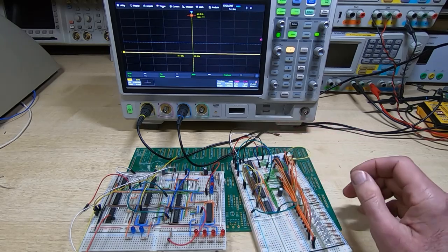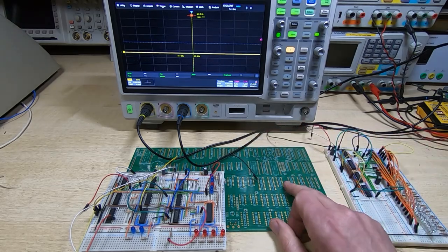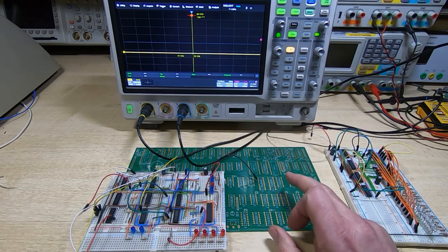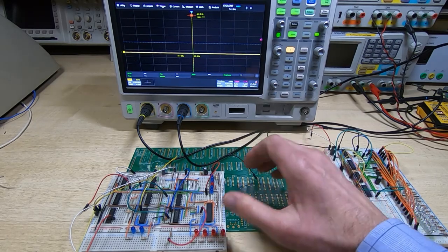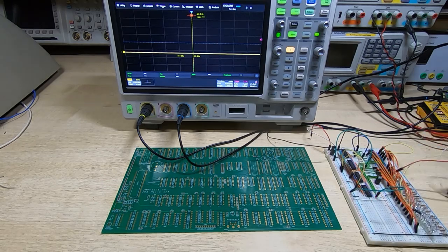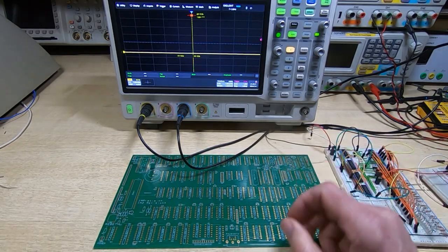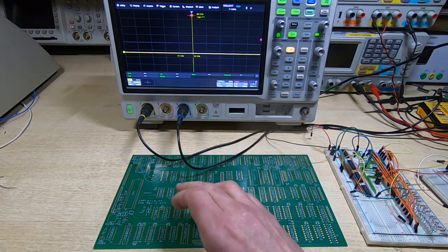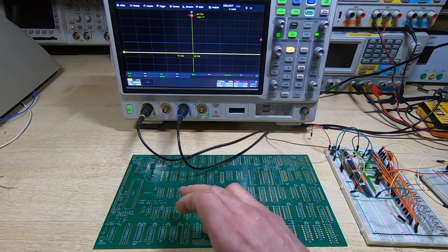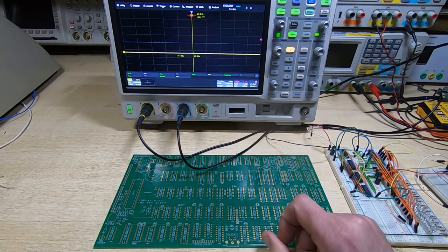So it's quite a lot to add, but I couldn't just add these circuits to the version 4 board for a number of reasons, but the main one was the buffering. So although there was some buffering in the version 3 and version 4 boards, it wasn't particularly extensive buffering, and certainly not sufficient to allow us to add many more devices. In fact, with this board, some of the Z80 types will not run properly. They'll run, but they'll be very flaky in operation.